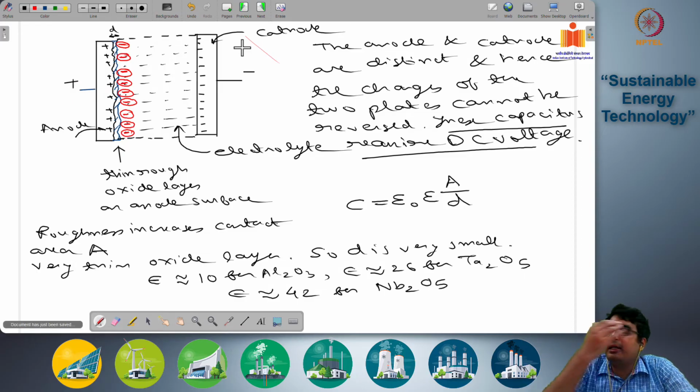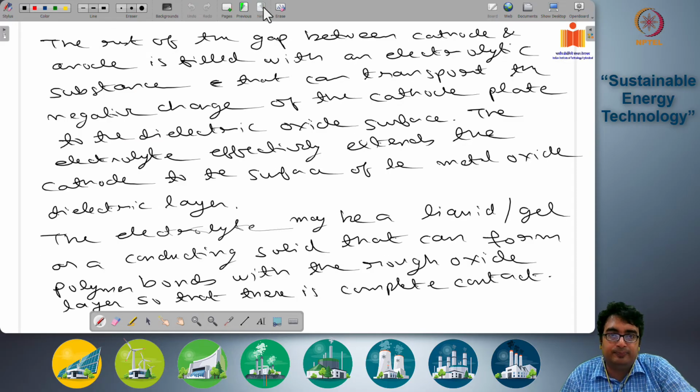Okay. So in a typical capacitor, you have two metal plates, the dielectric, and the two plates are completely symmetric. So it can work with an AC current directly because nothing changes if the polarity is reversed during the cycles of an AC current. Okay. These types of capacitors have a unique anode and a unique cathode. So the polarities of the two metal systems cannot be reversed. So that means that these capacitors require a DC voltage system.